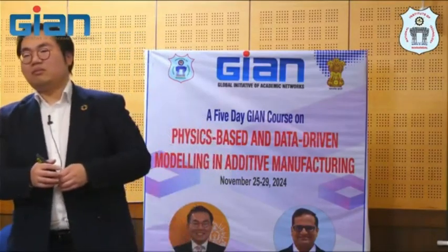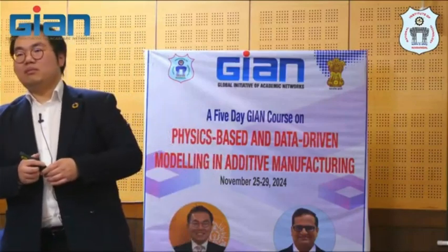And in the new alloy system, this segregation is not concentrated but uniform, in solid solution. So there is no preferred segregation in the as-printed soft condition. There is no segregation. Everything is in the solid solution.